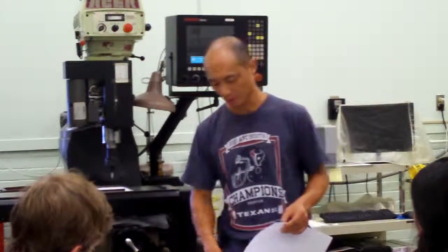Where is that on the drawing? Where is X1.5, Y1.5? It's the top of the circle. But the pen is still above the paper, not on the paper. So at M50, we change to G1 and drop down to Z0. So the pen is dropped onto the paper right on top of the circle.